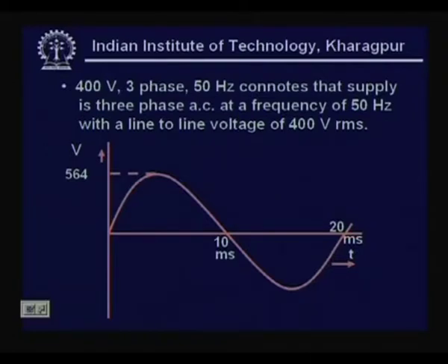Now, as may be observed, this is a sinusoidal voltage. This is a line to line voltage. It will become clear what a line to line voltage is when we look at the 3 phase connections. A little later, we will be looking into the generation aspect of a single phase AC generation, which shows us that the generation by nature is sinusoidal, and the easy way of expressing the complete sinusoidal voltage is in terms of phasors or RMS values, and it is known that for a sinusoidal waveform the peak to RMS ratio is root 2. Therefore, we have 400 root 2 as 564.